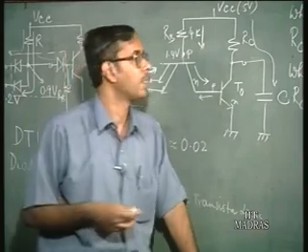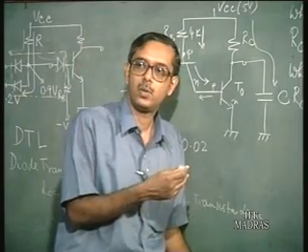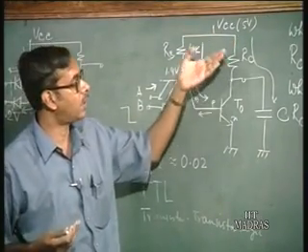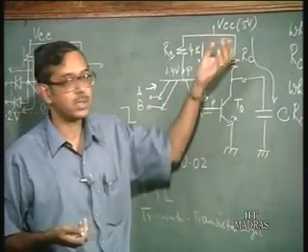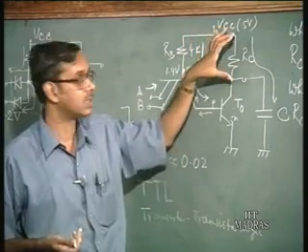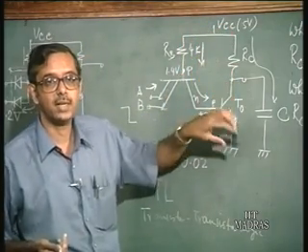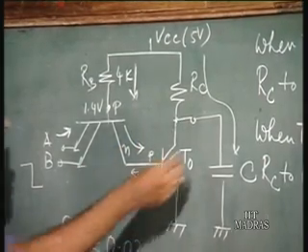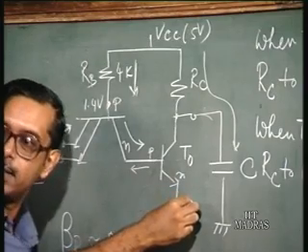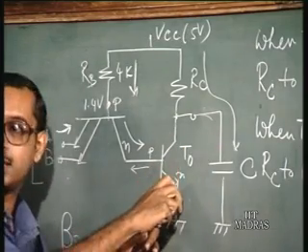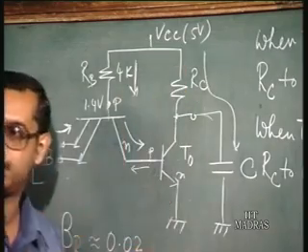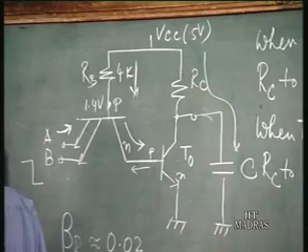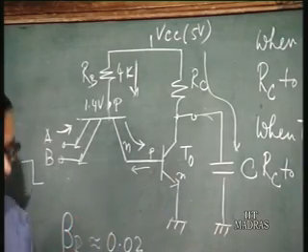So we require a circuit with what is called an active pull up. This resistance is called pull up resistance because the output is actually pulled up through that resistance. So this is the pull up device and this is the pull down device, because when the output has to be pulled down to low values, this capacitance has to be discharged through this. This turns on, and the capacitance discharges through it. So instead of a passive pull up, you require an active pull up. All right, you understood why we require that.